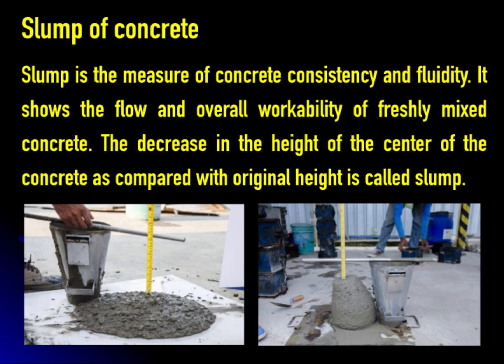The slump test is a widely used and simple method to evaluate the consistency and workability of fresh concrete. The test involves filling a slump cone with fresh concrete, then tamping with a steel rod about 25 times for 3 layers and lifting the cone vertically. The difference in height between the original and settled concrete is measured to determine the slump, as shown in the picture. Slump is not only an indicator of workability but also reflects the mixed characteristics and quality of the concrete.